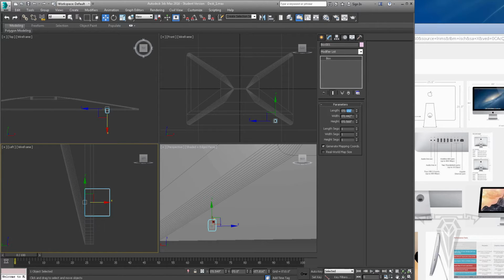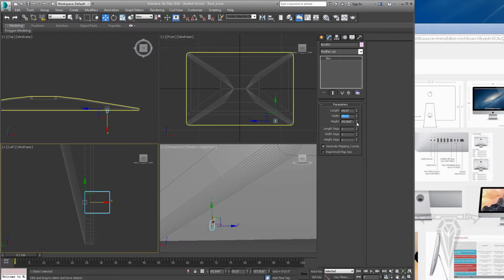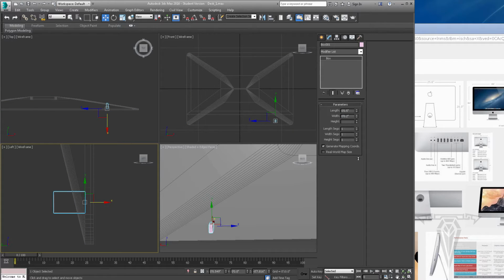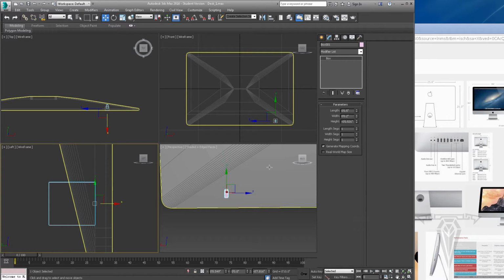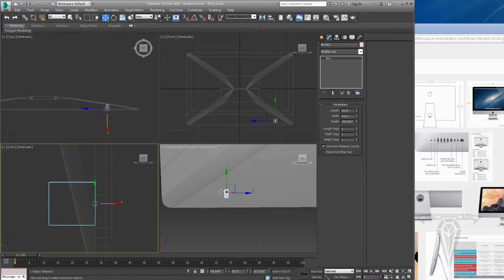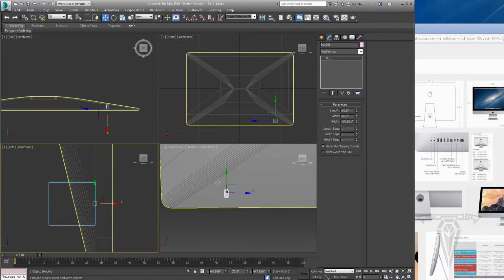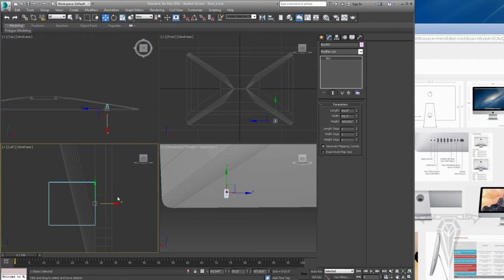I'm going to set this to 0.5, probably 0.2. That's the width and the height, and then the actual depth, I'm going to bring it up a lot. That's good right there. Okay, so I need the depth to stick out of the mesh, because we're going to use these boxes to cut holes in this geometry, basically like a cookie cutter. So we don't have to try to go through and model out each individual box in this geometry. That would be such a pain in the butt.